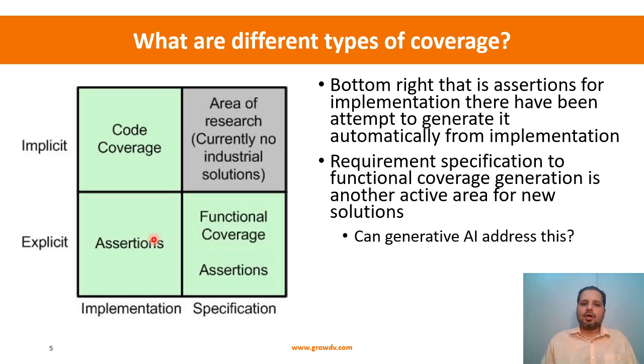So for those you typically utilize assertion based coverage, right? You write properties which model the temporal relationship of a waveform, because the design works in the form of waveforms, right? So you can model waveforms using properties, and those properties you can combine with the cover directives and use them for covering the implementation specific aspects.